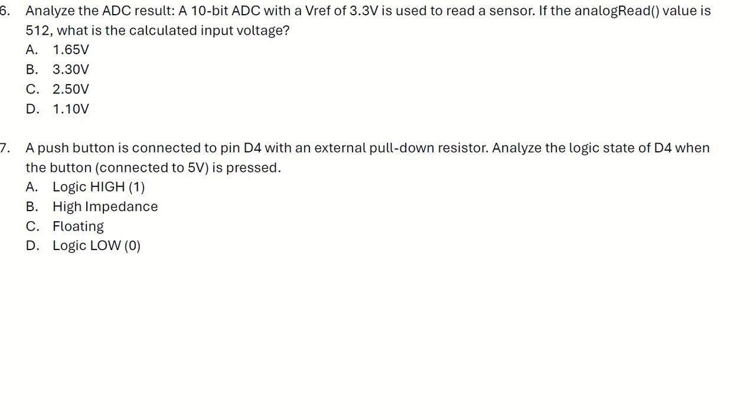So this one basically is Table 2.4. Okay, so you have seen the formula. So basically this one is slightly reversed. So we have a V reference of 3.3 volt. The example is 5 volt. Okay, and after that, you can also get the V out, divided by the V reference. Okay, and then we multiply by the 10 bit. 10 bit is 1023.